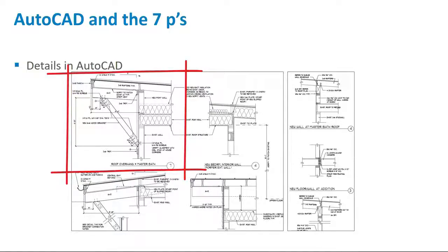You can either just insert it, as I said before, or you can take that into a family, into a detail family. Taking it into a detail family then means that you can link it when you're doing sections and elevations. Over time, what will probably happen is you'll start editing this in the Revit family and start taking out some of the lines that you'll end up with in here.